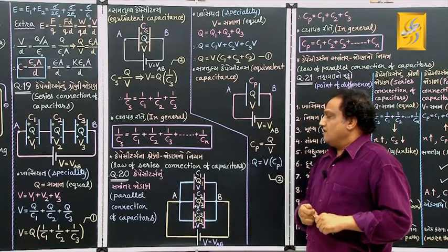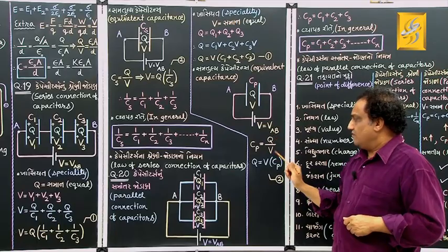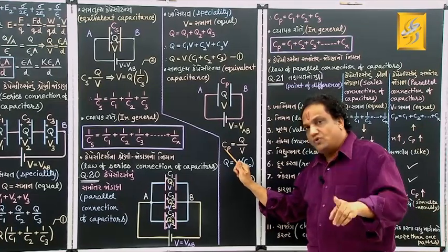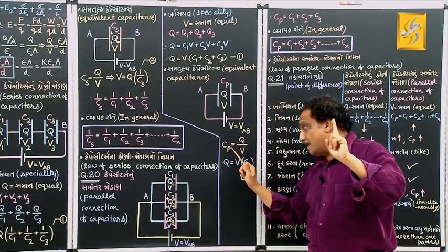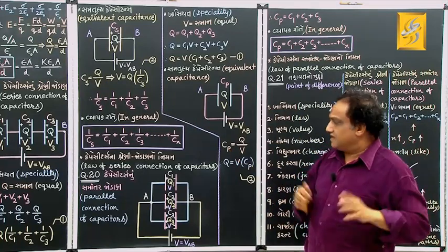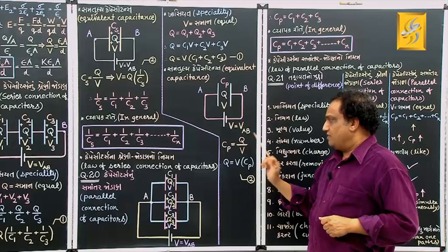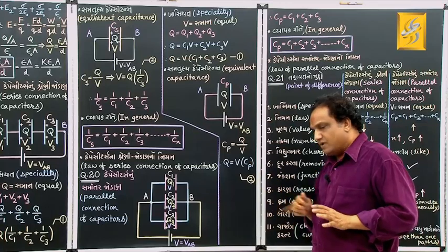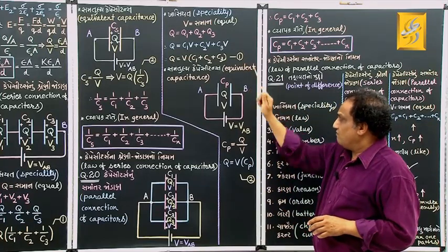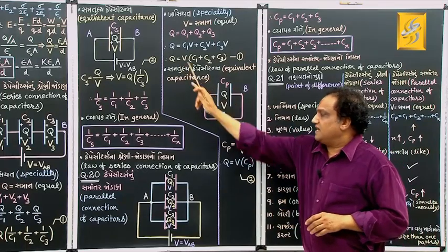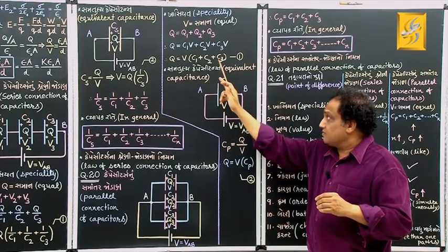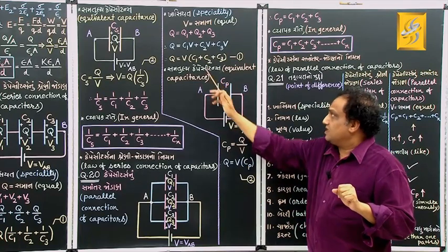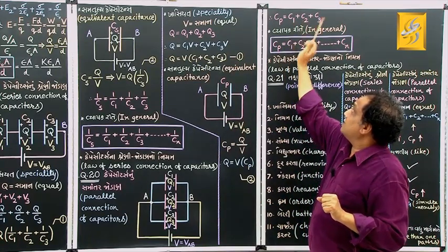Okay, fine. Now from the basic definition, C equals Q upon V, but instead of C I should write CP, correct? This is going to give you the equivalent capacitance of the given parallel connection of capacitors, correct? Fine. Now find out Q from here, it will be V into CP. Give it equation number 2. Now from 1 and 2, come on, compare. Left hand sides are the same, then right hand sides must be the same. Then on the right hand side V and V they are the same. So CP must be this much, that is C1 plus C2 plus C3.